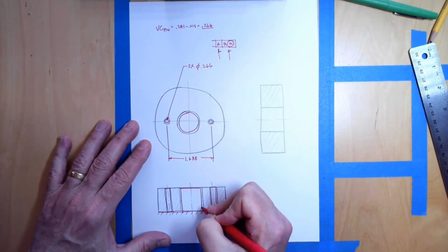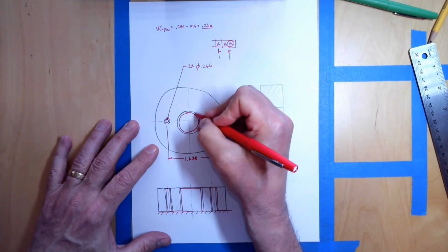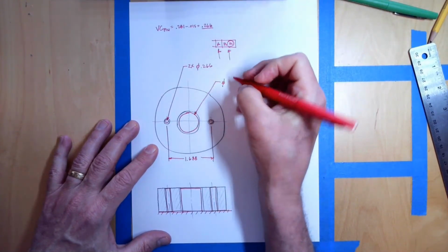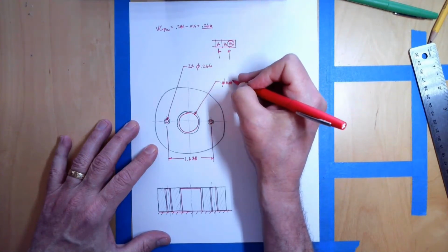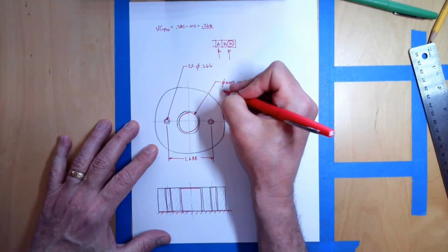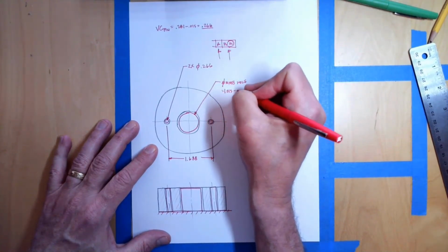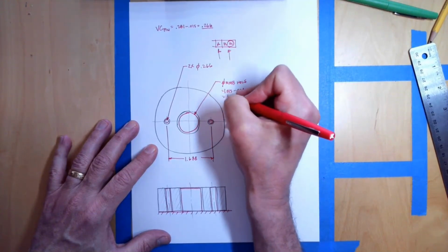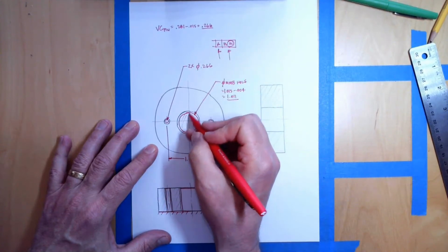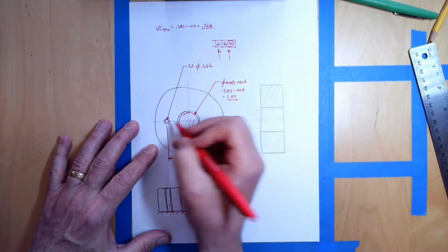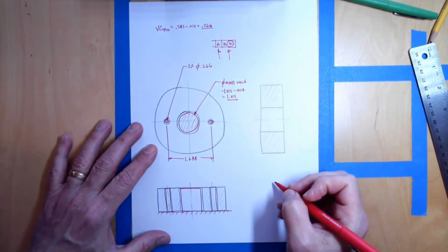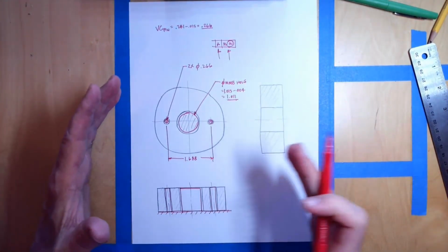And the pin is going to have a diameter of the MMB size of the hole, which is equal to 1.015 minus 0.004 equals 1.011. So the size of that pin right there is 1.011. Okay. So that's the functional gauge.